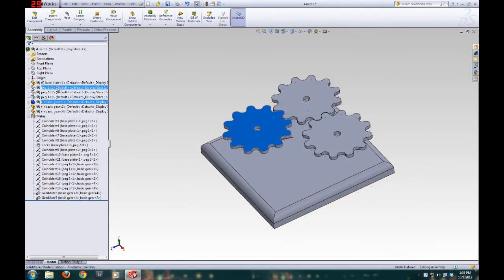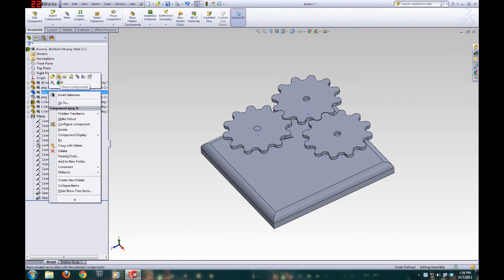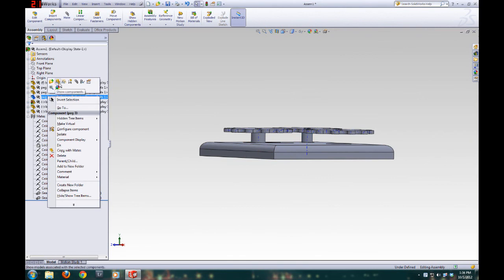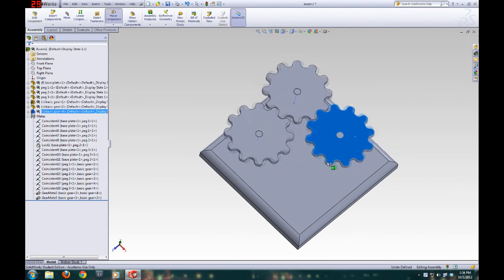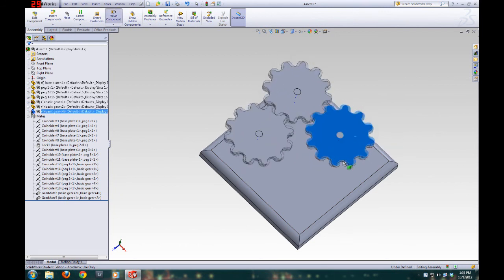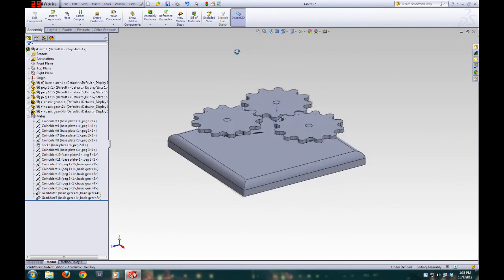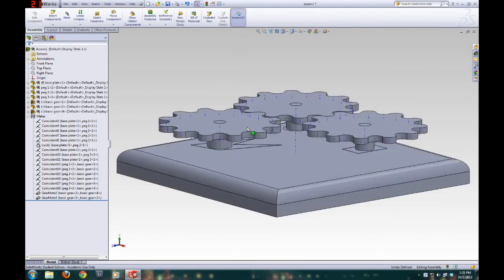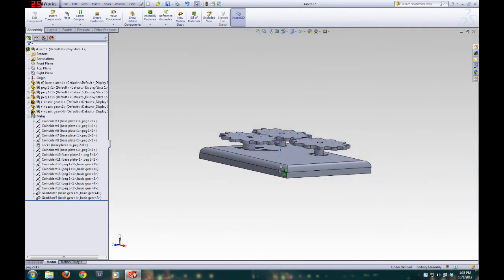So that, if we go back in here and unhide our pegs 1, 2, and 3, here comes the third one. Now that is our assembly, and we've created constraints that allow us to rotate gears. Now to properly turn in this homework, we want to show that each part has been placed properly, and that's kind of hard in this view because you have to get down to a shallow angle to see that the pegs are in there, that they're properly aligned, but then you can't really see the gears, and it's just awkward.